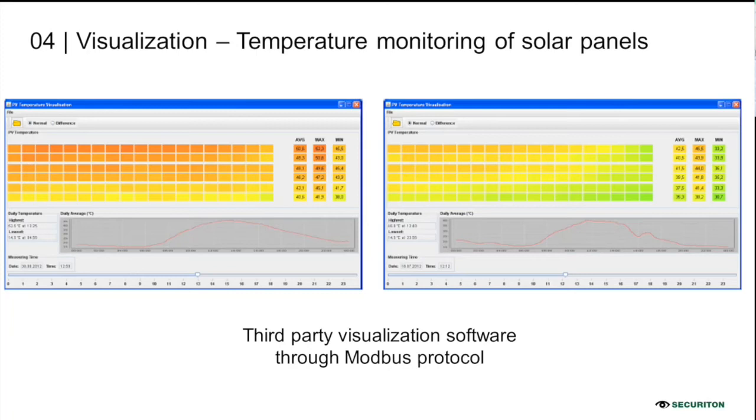But in our case, each of our sensors is actually producing a real temperature. So this can monitor, and when the threshold of a certain temperature prescribed here is reached and crossed, then we can associate the relevant relays from our D-list, and that can actually tell the third-party system to switch on their cooling system. So that's also possible with our system. At the same time, I need to mention the external sensor works the same as well. So the SEC15 as well as the external sensor works perfectly in terms of capturing the temperature monitoring as well.